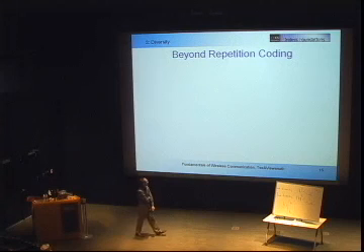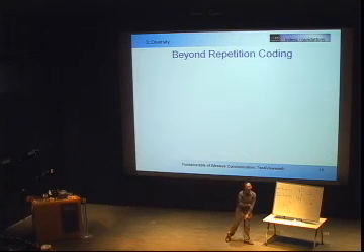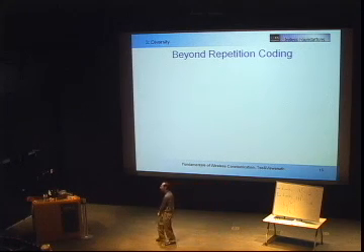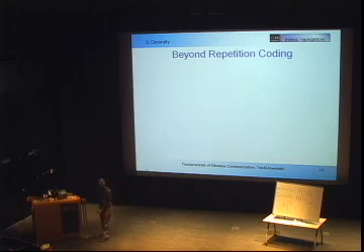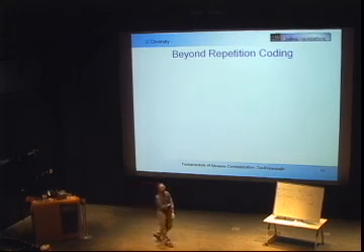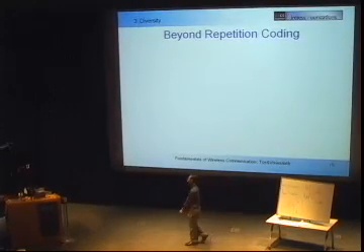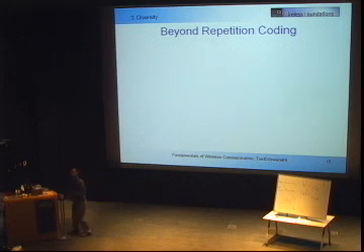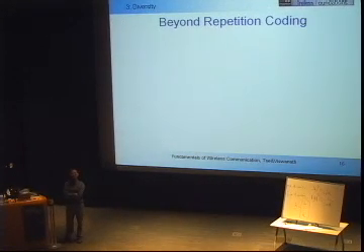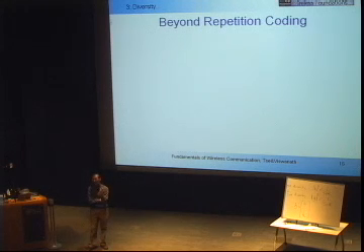Okay. We have a problem here, though. We have excellent error probability performance, but we lost out in a lot of stuff. What did we lose out? What are we doing here? What is repetition coding doing for us? Yes, but at a higher level, repetition coding is sending one bit, right? Or one information symbol, every L channel uses. So as you increase L, the data rate goes down.